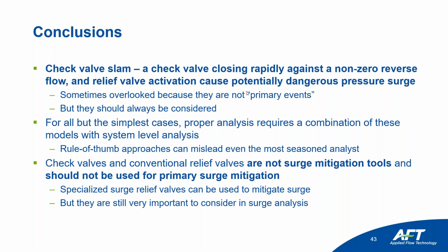So they would actually analyze it and be able to tell you, oh, maybe this is too corrosive, or maybe you would have chemical reactions in this or something like that. Usually you would rely on the relief valve designer or expert in order to decide those. I'm not as familiar with it. I would assume that they can be used, but it's a case-by-case basis.